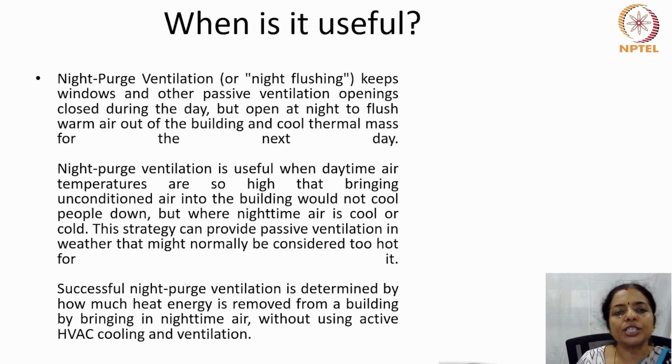So when is this useful? Night purge ventilation or night flushing keeps windows and other passive ventilation openings closed during the day but open at night to flush warm air out of the building and cool thermal mass for the next day.